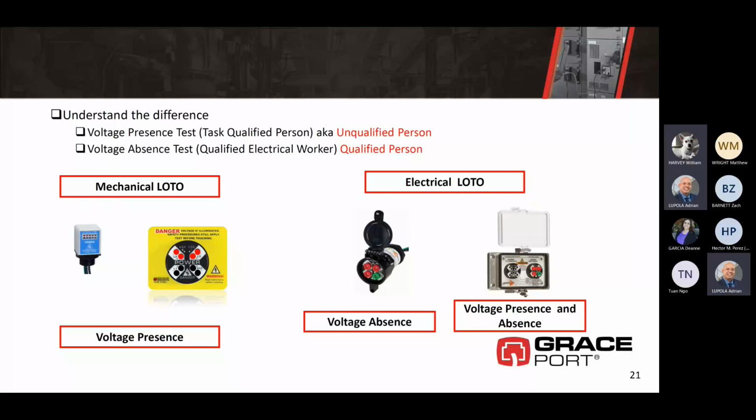Next slide. And then the other part of this is, again, downtime. Lockout tagout can be an onerous process where you have to put the bunny suit on. They're supposed to put the meters inside and verify the absence of voltage. So we have these voltage indicators here. This is just on/off, typically on disconnect switches, so I can see that there's power coming to a switch, or it also works as a blown fuse indicator on the outside for mechanical lockout tagout. With this voltage test station, I have the voltage indicators to see the lights, and then outside the panel I have a place to put my meter probes to check for absence of voltage. So I can take a half-hour lockout tagout procedure and do it in under 5 minutes without having to put the bunny suits on to go in the panel and do it correctly.